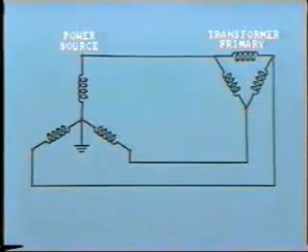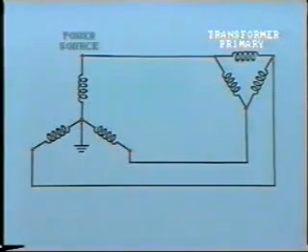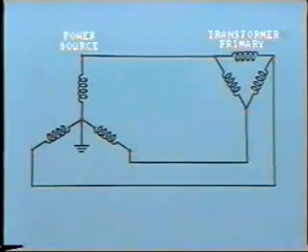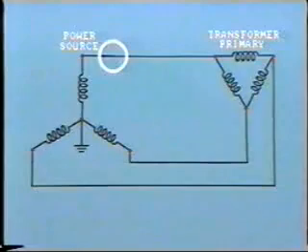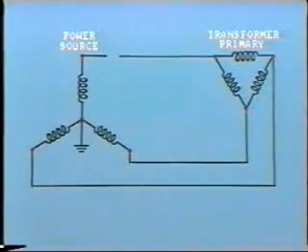Typically, this can occur where we have a delta-connected primary of a distribution transformer. In this system, the distribution line is being fed from a Y-connected secondary with the neutral grounded. As this is a distribution line, fuses are often used, so let's consider the situation where one fuse only blows, such that we have one phase open-circuited. This situation can also occur where the lineman opens feeder switches one phase at a time.